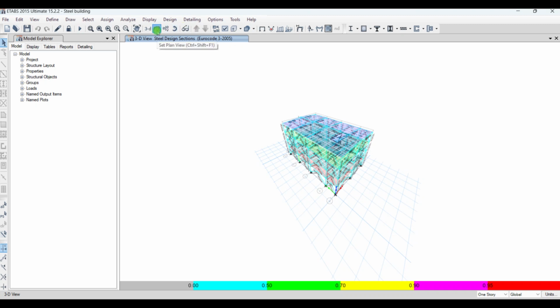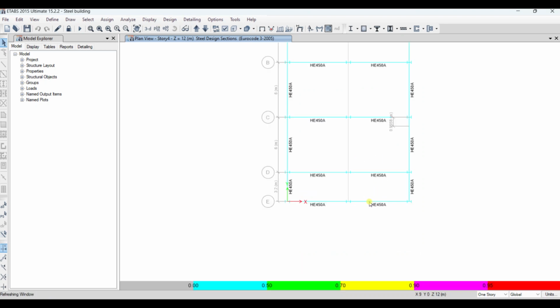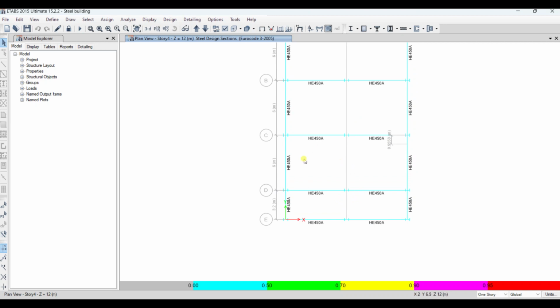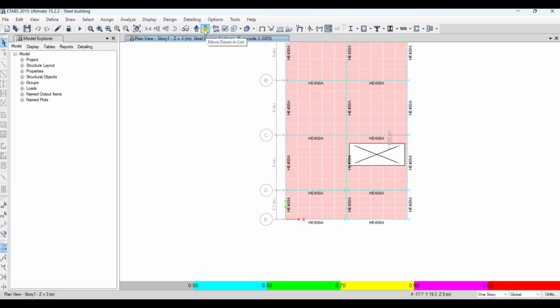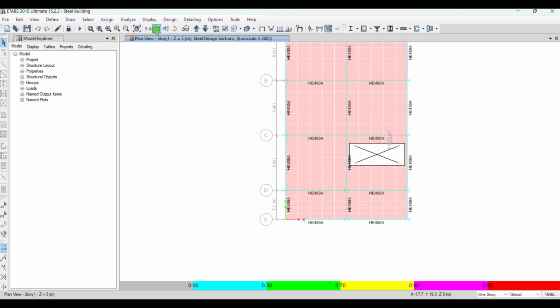An I section is given, so we can show these sections. So here is HE 40, this is an I section. Likewise we have columns and beams from this section. This is the auto list. From the auto list it was decided, and on the basis of demand the software calculated, and we have come out with the most economical and smallest-area section to bear all these loads. So all the floors we have calculated, and in this case our model is completed.